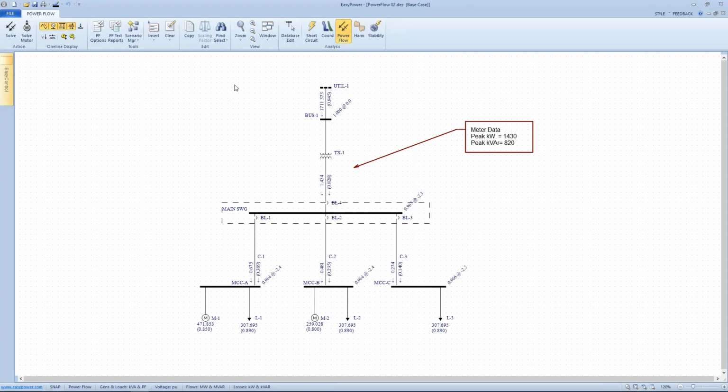So frankly, we're just barely touching on the capabilities of the tools themselves. For instance, if we wanted to look at voltage losses, we can see what the losses are across the transformer and across each of the cables. And where we're finding discrepancies there, we'd want to go back and understand the source. And this is the losses per branch in real and reactive power. Here's any overloads that I have. So clearly here, I'm within 10%.